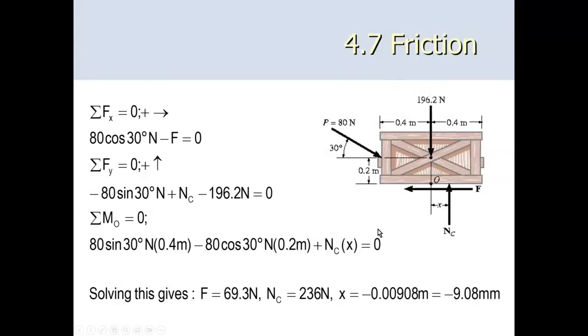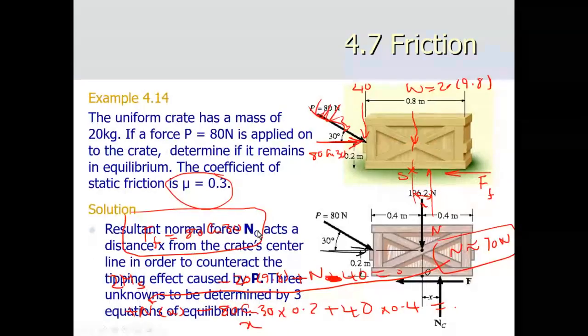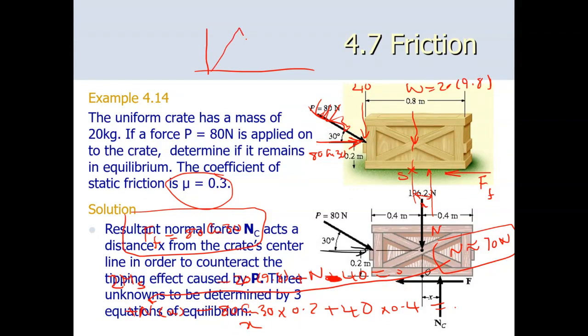And then more importantly, now I can find out whether this friction force is larger than the onset, because at the onset, the friction force is what? The friction force, if I plot this curve, this is the onset. Only at this point, friction force is equal to mu static multiplied by N. So if I multiply 0.3 by that N times 70, it gives me a force, and then I can compare this force with the real force.